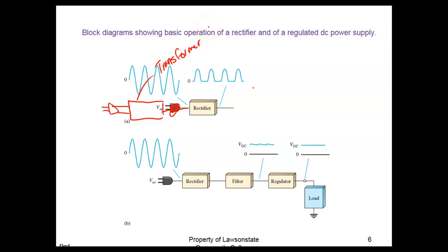And a transformer is actually going to come over here, and this is very, very important to choose the right one. So not only is it going to have to supply the required voltage for the load, it's also going to have to provide the required current for the load.